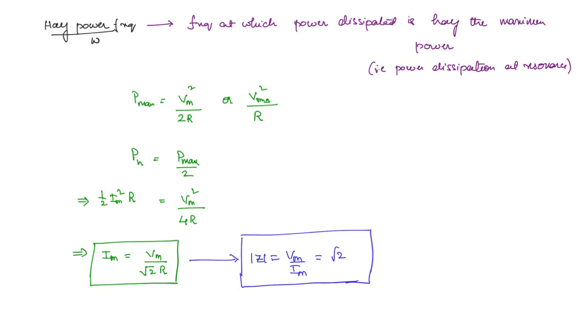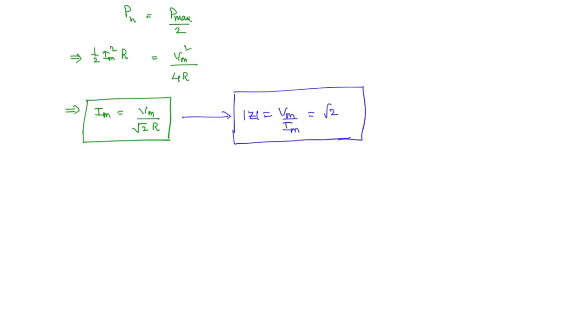So finally we want to find out the half power frequency. You will see that you will get two half power frequencies. So we will see what that is. Mod Z is going to be equal to root over R square plus XL minus XC whole square.